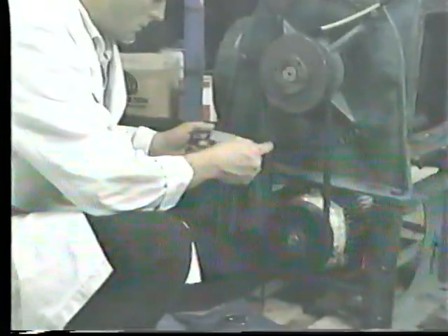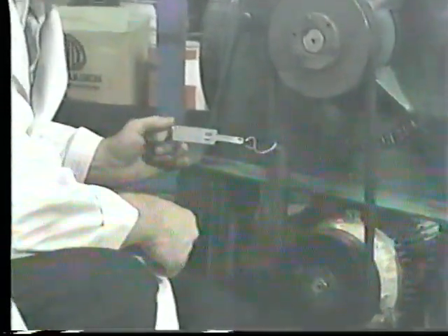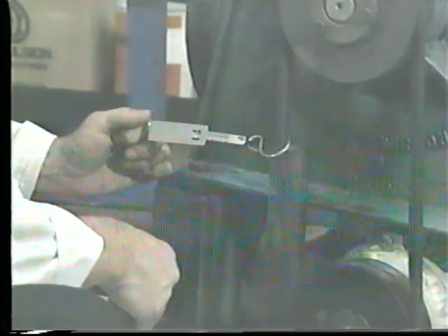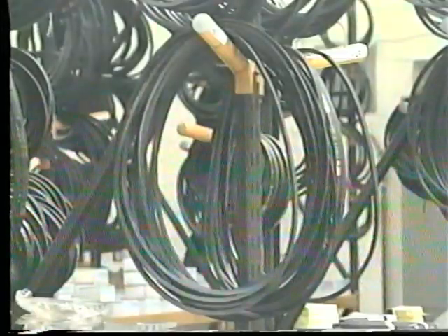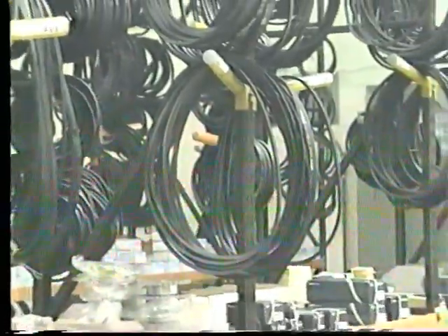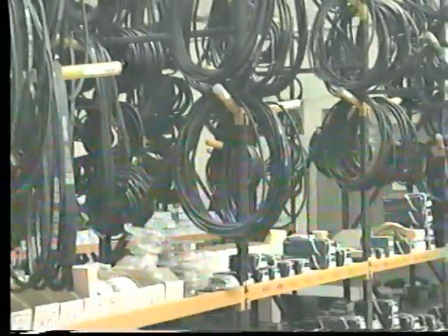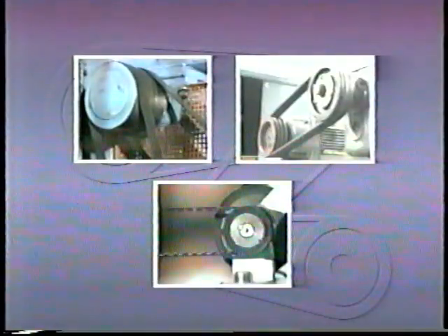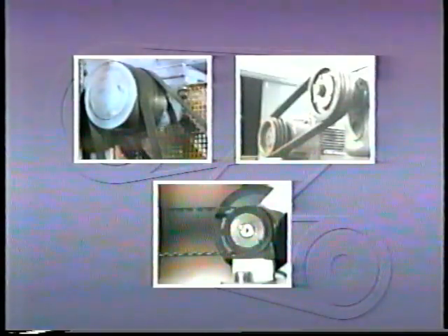The correct tensioning of all these belts is important, but especially for V-belt drives. Belt dressing is no substitute for the correct tension. Finally, storage. All types of belts should be stored in a cool, dry place and where they will not be creased or bent. In this program, we have looked at 3 types of belts used in power transmission drives: flat